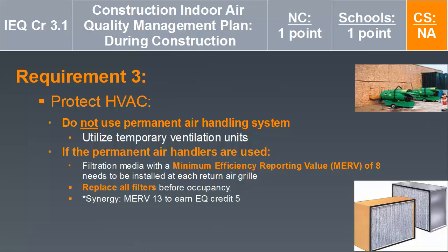Another requirement of SMACNA guideline is to protect HVAC. Do not use permanent air handling systems. Instead, use temporary ventilation units, as shown by these Sunbelt units in the image.